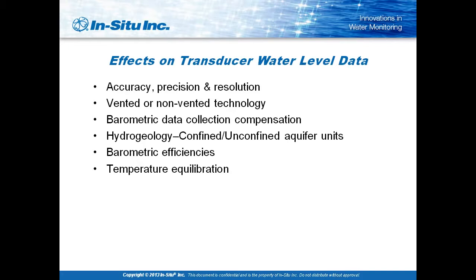You want to make sure that the instrument has equilibrated in temperature to the temperature in that water well. Plus, if it's on a cable, that cable has stretched out and relaxed and reached its full length. Otherwise, you'll start to see some slippage in early data.